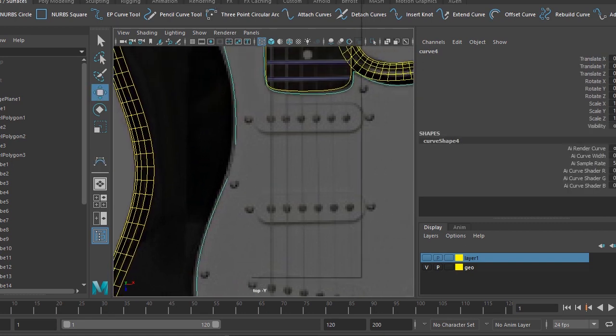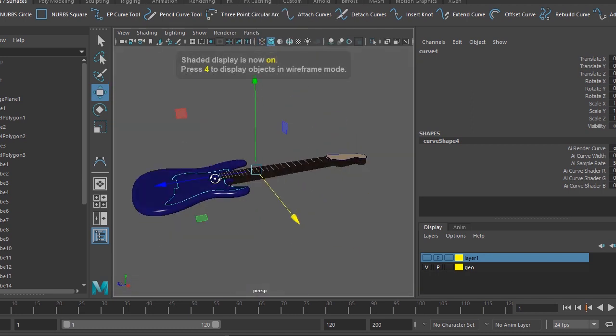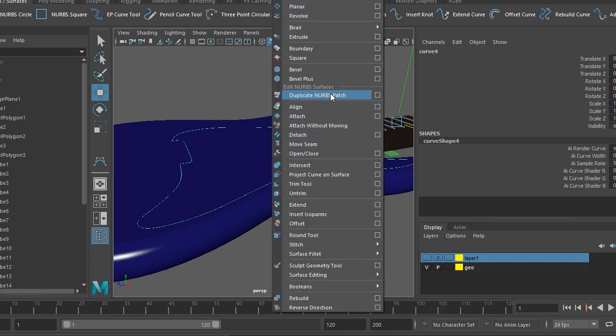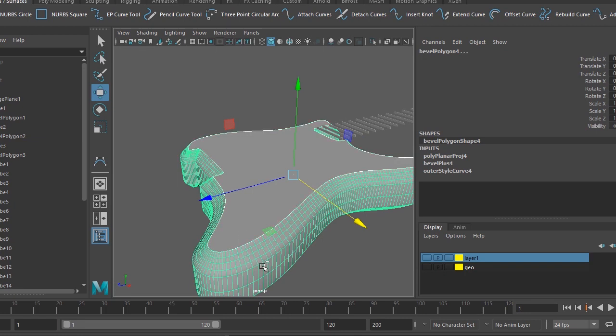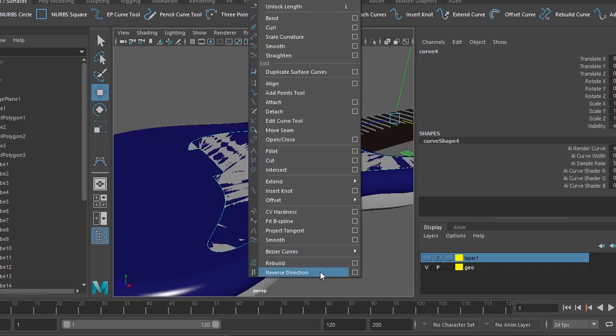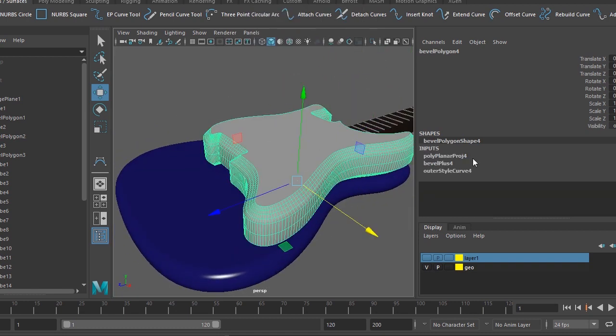Now there is an opening here. I'll be using open close curve, and this curve should get the model, and you see the extrusion is on the below. So I go to the curves and then use reverse curve direction, and the extrusion happens on the other side.